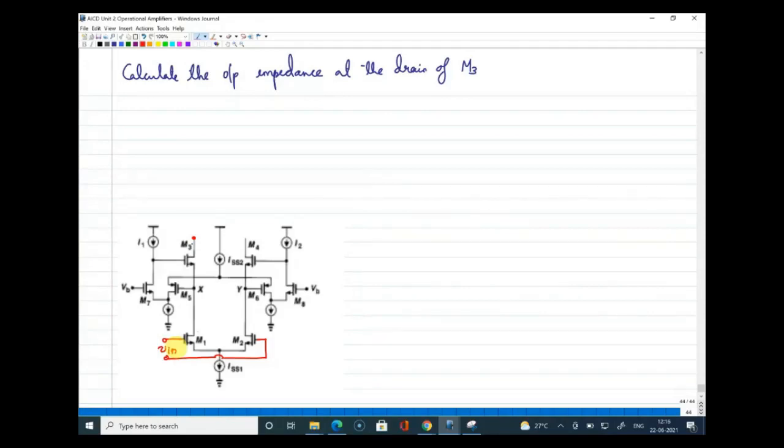The very first thing is, how will we identify the main amplifier? We identify it by looking at the input transistors. You can see M1 and M2. Vaishnavi, yes, I saw your response. Akash, I think I responded. M1 and M2 are the input transistors because the input signal is directly given to them.